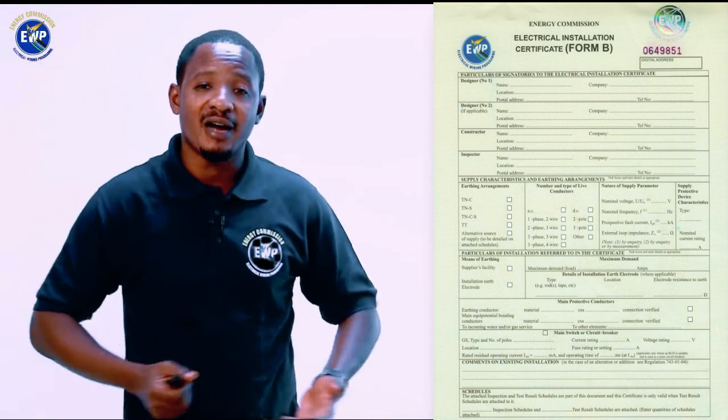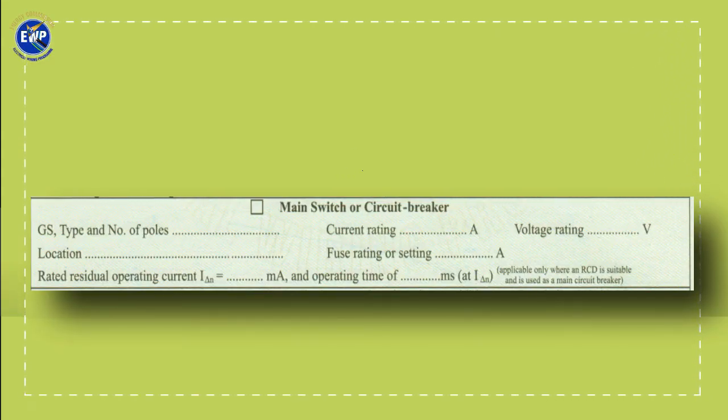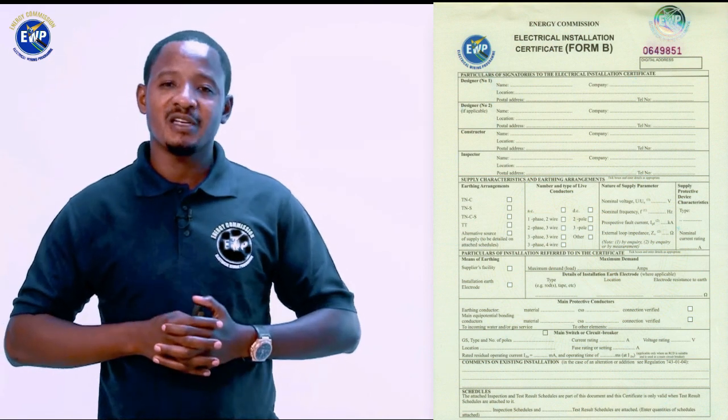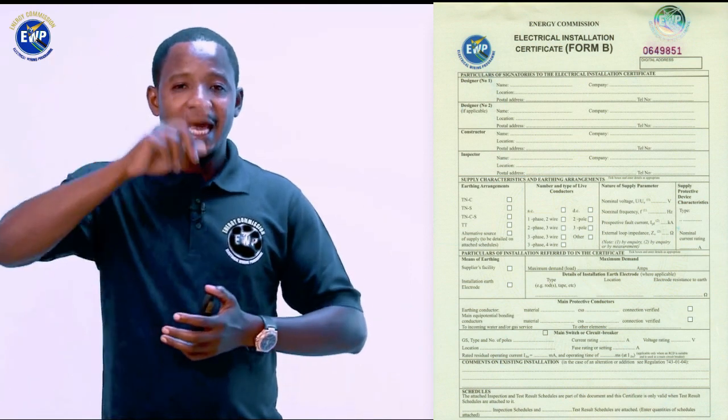So maybe 125 amps. Now, if your incomer happens to be the type that has a residual current device, which is an RCD, you are required to write the rating of the RCD, which is mostly in milliamperes, and then you're also required to write the trip time. And the trip time here is the time it takes for the RCD to trip. And that is mostly a live test. So for service application, you find that there will not be power for you to be able to do that. So we request that you don't leave the place blank, but you can write NA.